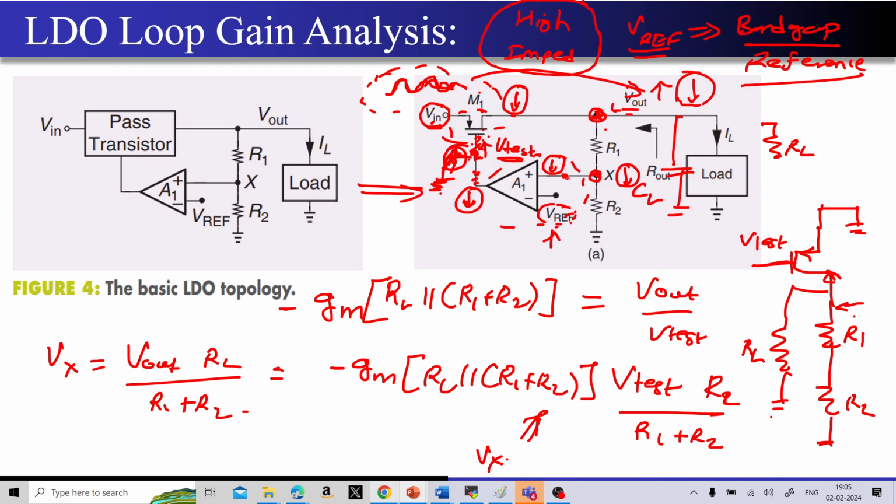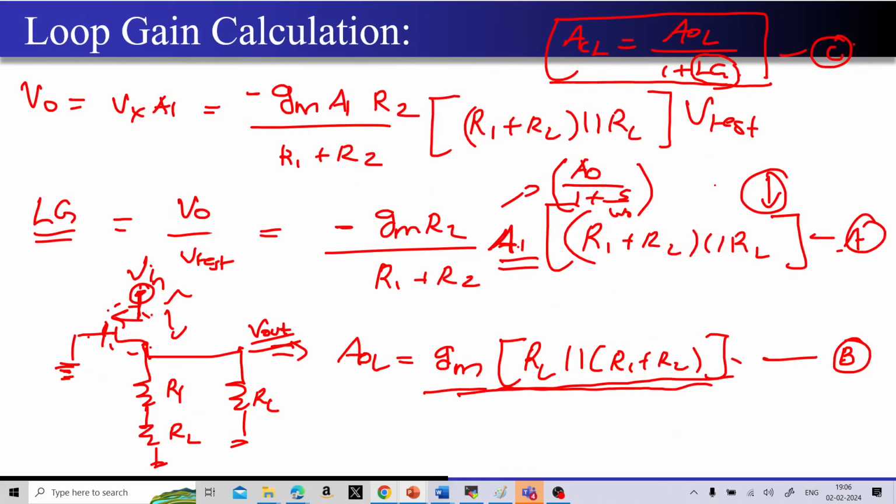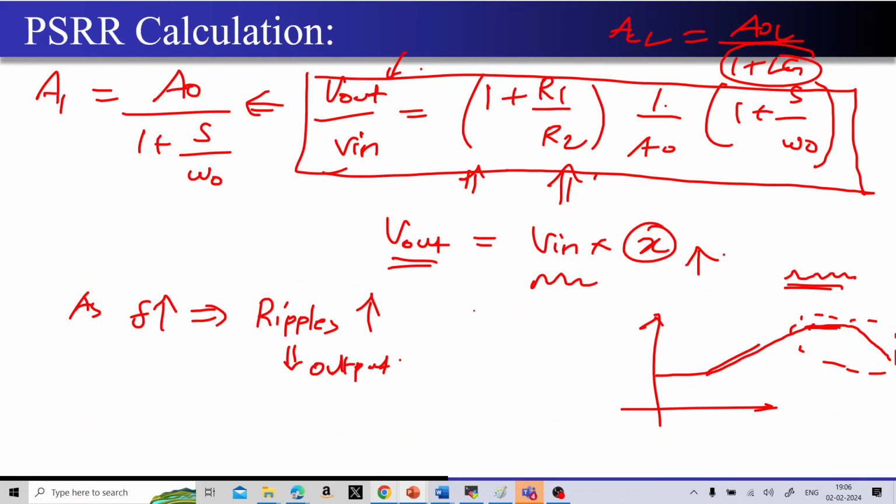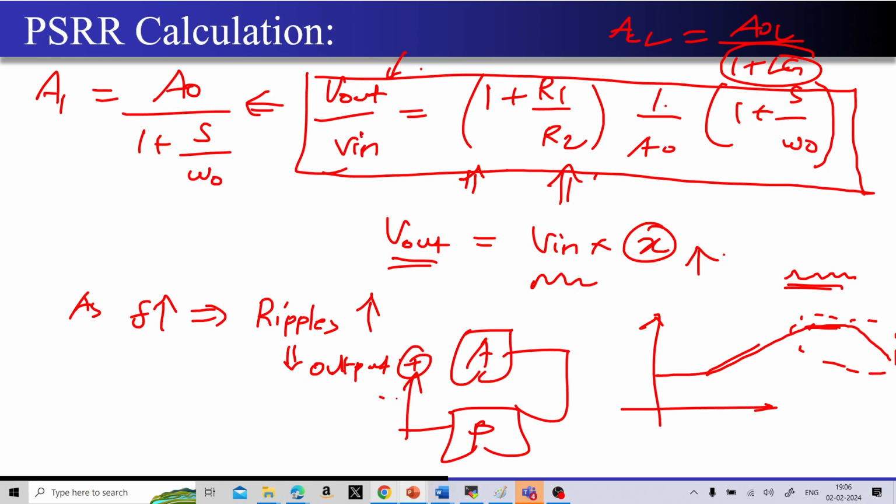You can also break the loop here, but you should understand whatever signal from the feedback is being fed. Let me have the diagram again, just a minute. Let me draw it somewhere. Yeah, so this is your A, this is your feedback factor beta. Have a look at this summation. This is the Vin where I was applying Vin, and this is the negative feedback that I was applying. So to calculate the open loop gain, I just nullified this feedback directly. I don't want this feedback to come up, and that is the way I've tried to find the open loop gain.